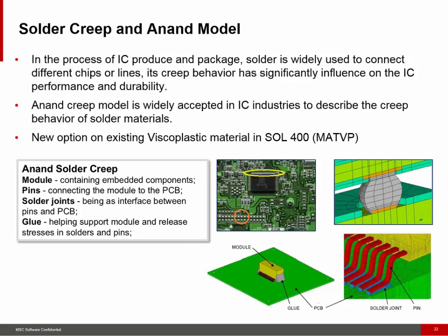The Anand creep model is widely used and accepted in this industry to simulate the performance and the behavior of solder material. So we've added the Anand creep model as a new option on the existing MATVP, the viscoplastic material in solution 400. So there's no new material entry, it's just an additional option on the already existing MATVP. Here is one example where you can see a solder joint between the pins and the PCB on an integrated circuit.